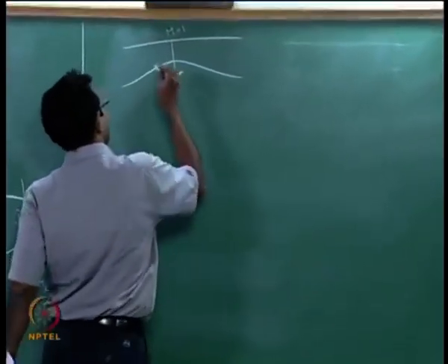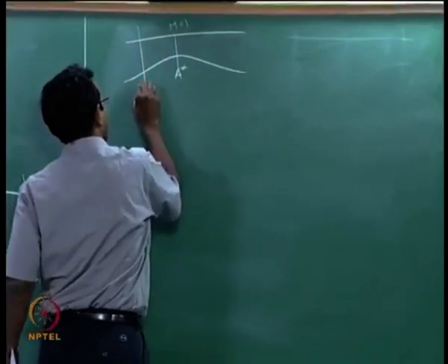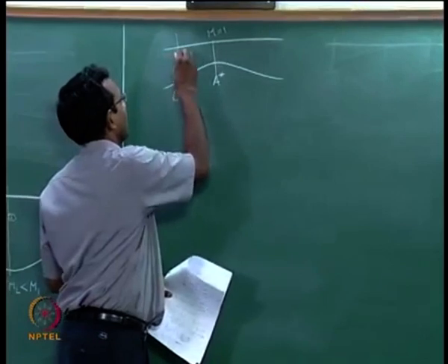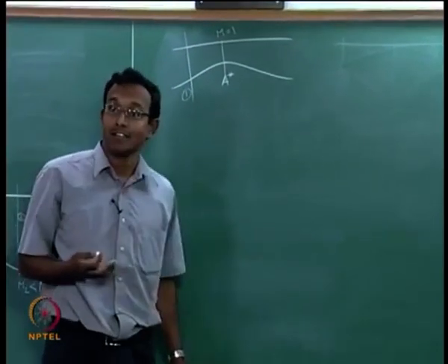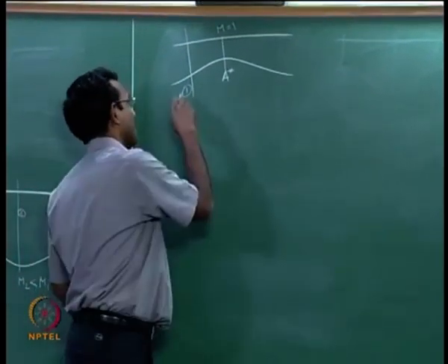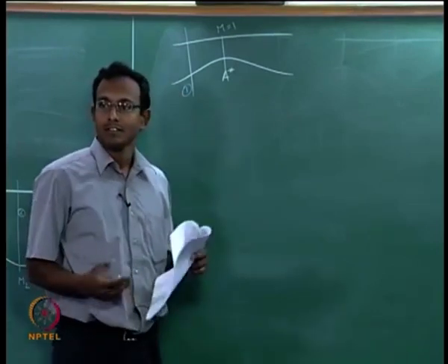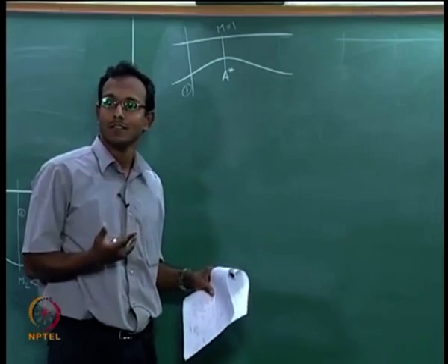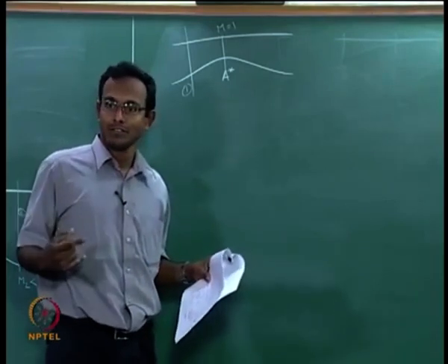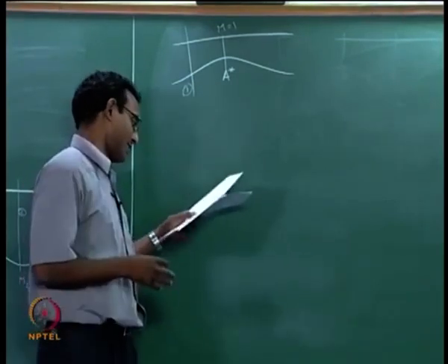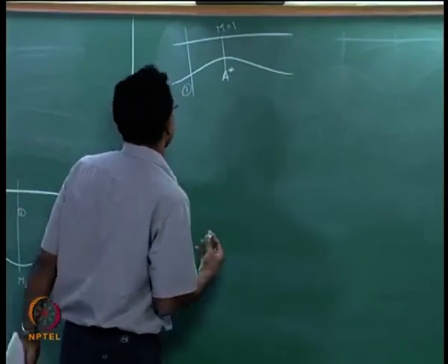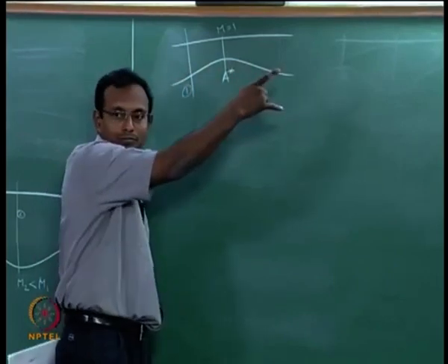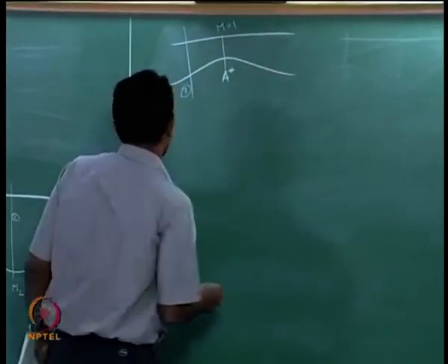Now our job is to go and find, let us say section 1, I want to know the Mach number for this area, whatever area A1 is given, let us say I want to find the Mach number M1, that is the overall idea. How will I find it? So now I will start using the integral equations and trying to get to some point where it will look like I know how to solve this problem. I have already assumed that it is an isentropic flow and I am starting to solve the problem.